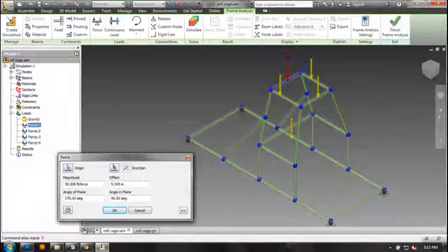Once all the joints on your frame have been notched or mitered, you will begin by creating a new simulation. You will add fixed base points to the bottom of the frame, as well as fixed loads across the top of the halo on your roll cage. Please note that Autodesk Inventor will automatically add the forces of gravity weighing on your car.